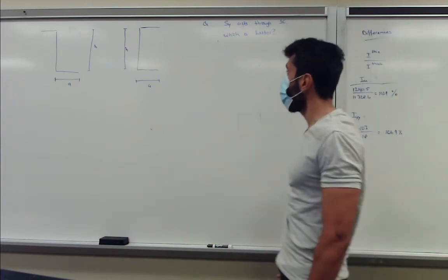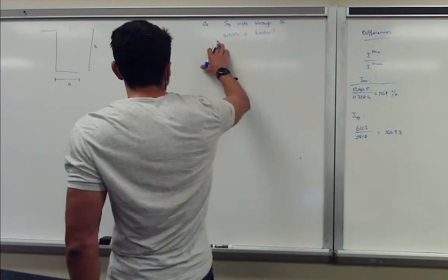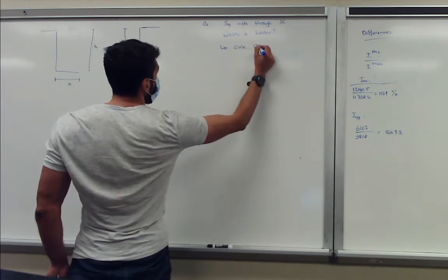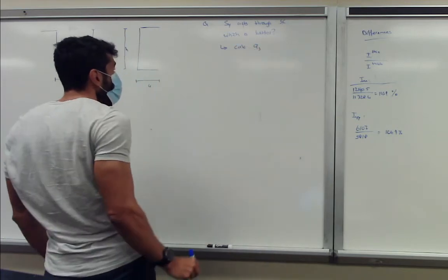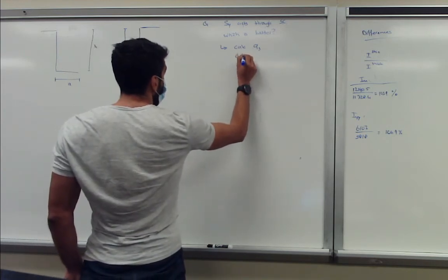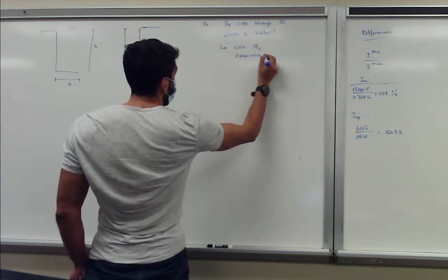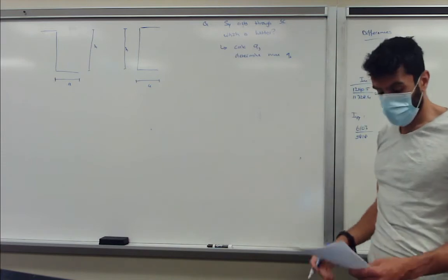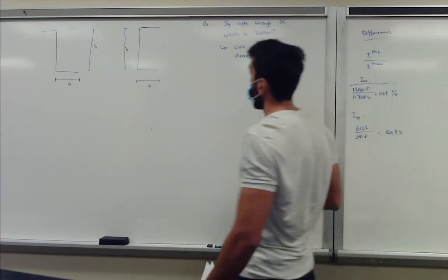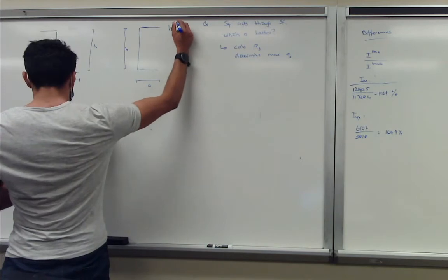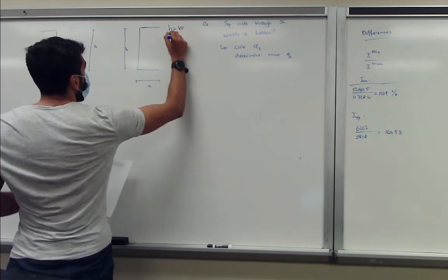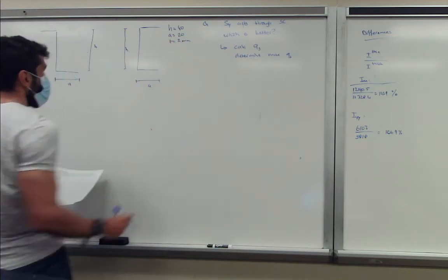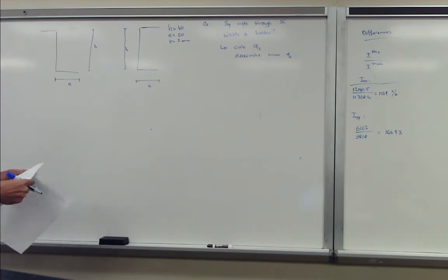So what we have to focus on is we have to calculate our shear flows, q_s, and determine max q_s. Okay. Now we have a couple of numbers given as well. So H is 40, A is 20, t is 2 millimeters. And we can assume thin walled.